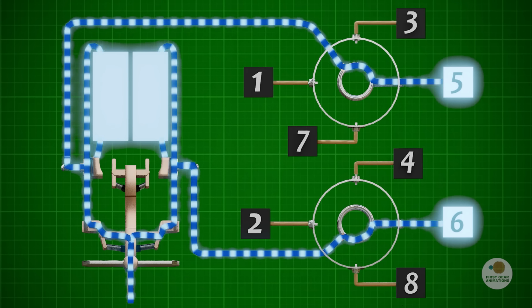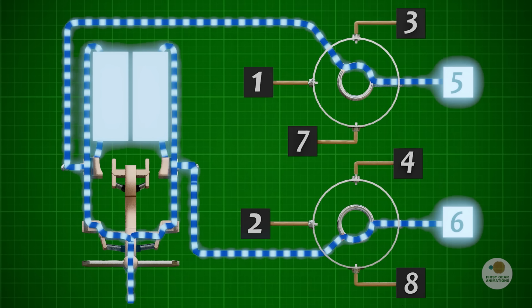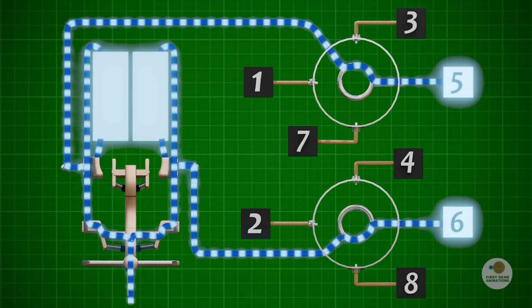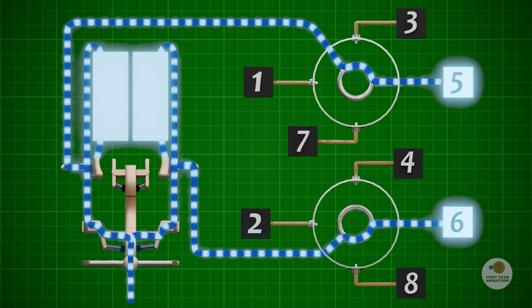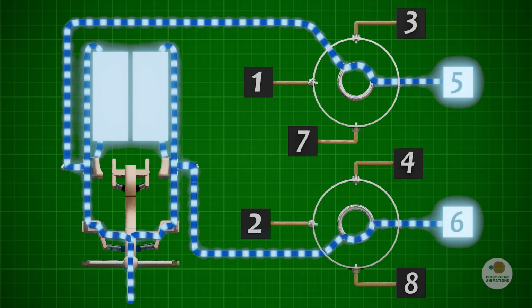Here, it simultaneously connects to both the old tap 6 and the new tap 5. At this exact moment, both transition resistors become active in the circuit simultaneously. These resistors limit the circulating current between the two taps and prevent dangerous arcing.